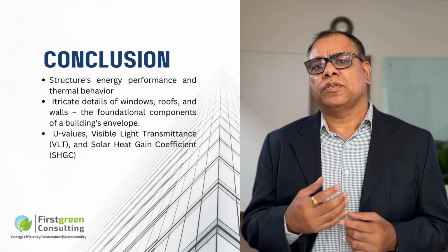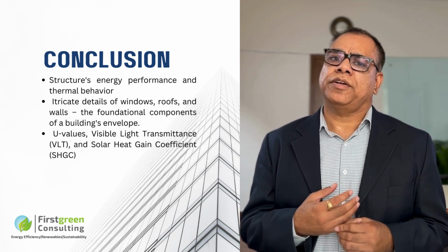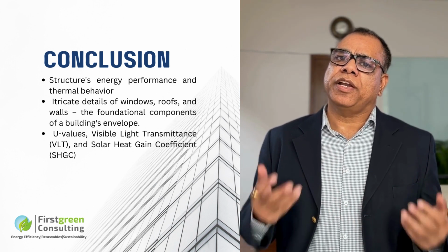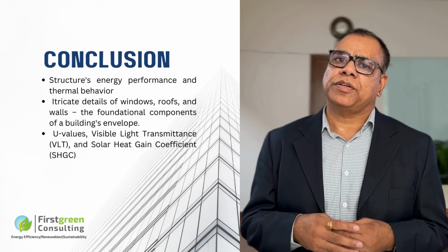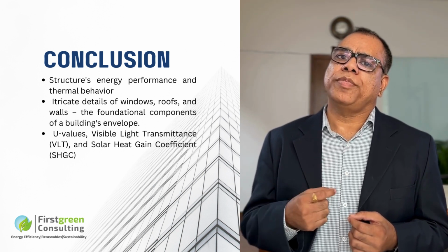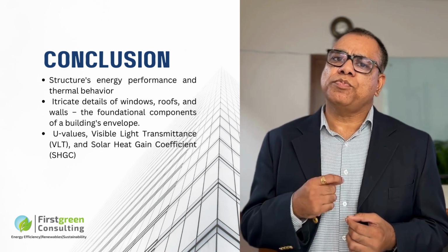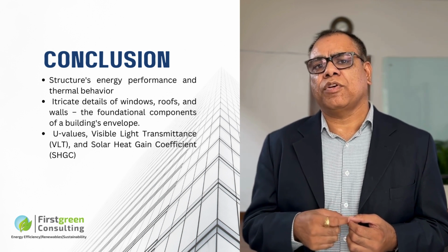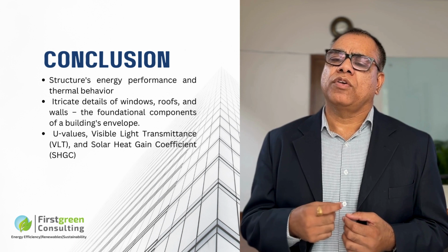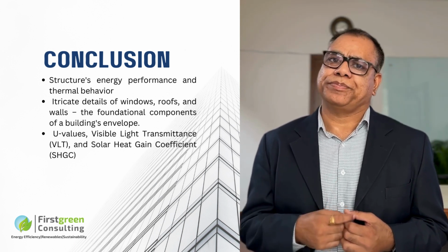So friends, the window, wall, and roof, these three elements constitute the building envelope, which protects the building from the outside environment. And especially the major concern is how building heat gains are taking place. And these parameters which we have assigned in our model as part of the property of window, wall, and roof will decide the building heat gain while we conduct the simulation.